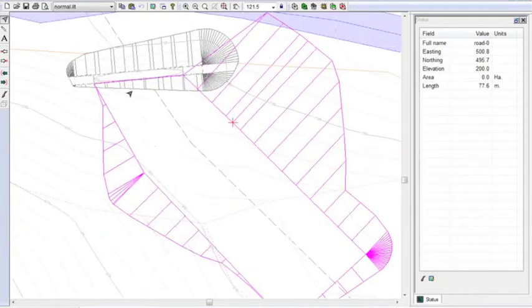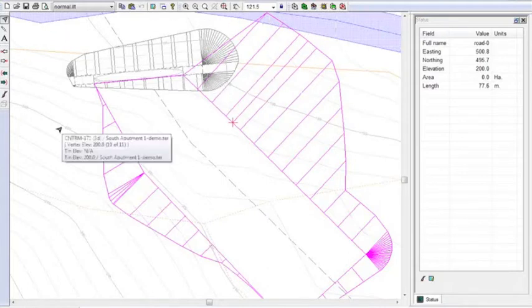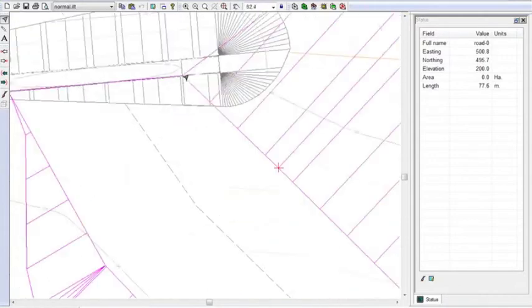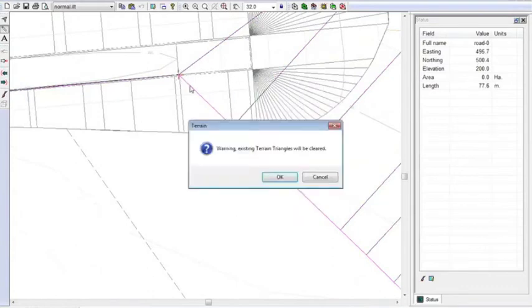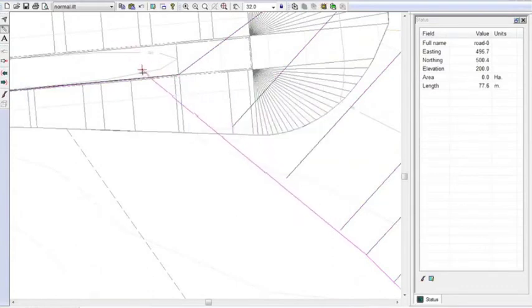So you can see here that it's grading. Oops, it looks like it's fallen over the edge of the ballast wall there. Otherwise, it looks quite reasonable. And I can fix that up either by moving the ballast wall out, that would involve changing my background terrain, or this is what I'm going to choose to do. I'll just move this point here in a little bit, like so.